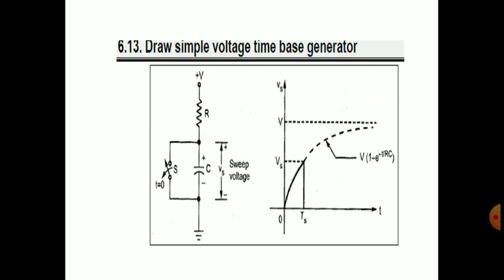Though there is a drop, as the capacitor charges, the DC source, as time passes, because of the drawing of energy from the DC source, will decrease in voltage level, and the KVL equation in this loop will be satisfied, right? After a very long time, the voltage drop across the resistor becomes 0, as there is no flow of current through the resistor, and the capacitor reaches the maximum voltage, that is the supplied voltage.